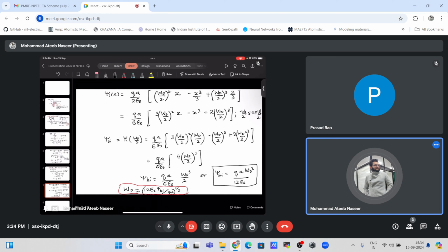If we are given the charge profile, we can obtain the related field and the related potential variation by just solving the Poisson equation, Gauss law. So this was one of the practical applications of this linearly graded junction region.